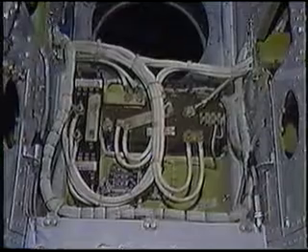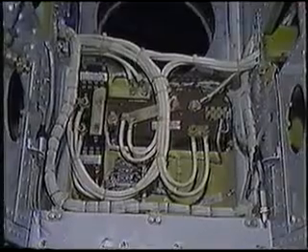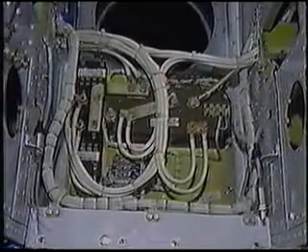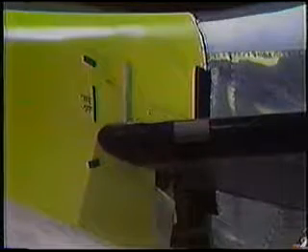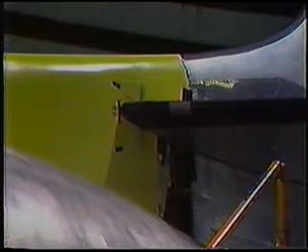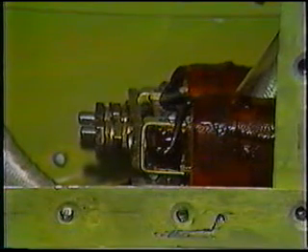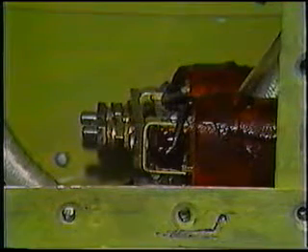Because wires are routed in bundles, tightly grouped together, the small magnetic field of one wire may cause a small voltage to be induced into an adjacent wire by a property called transformer or inductive action. Suffice to say that these induced voltages are small and practically unmeasurable. Since most circuits in the aircraft function on 28 volts and consume a measurable amount of electrical power, they do not even notice these tiny induced voltages. On the other hand, conductors carrying millivolt signals, such as the fault signals, can be affected. These voltages induced by transformer action are better known as spikes.